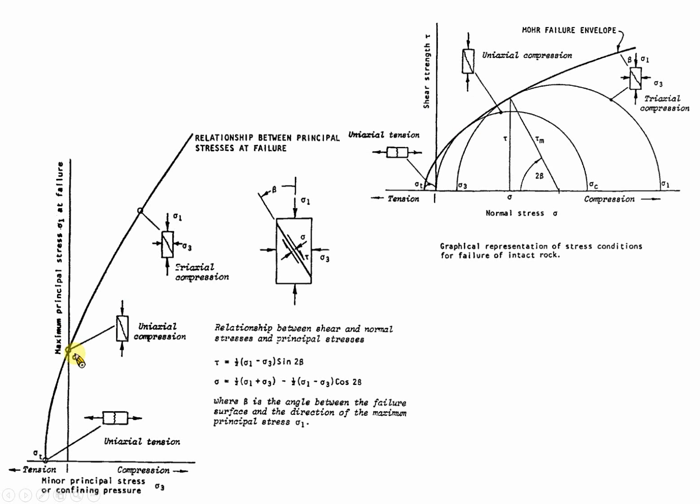For this, we do not really guarantee any specified failure plane with any specified angle. We do not really know what the angle of the failure plane will be. We are not pretty sure, unless you accept the assumption from the Mohr-Coulomb failure criterion. Then you can determine it.